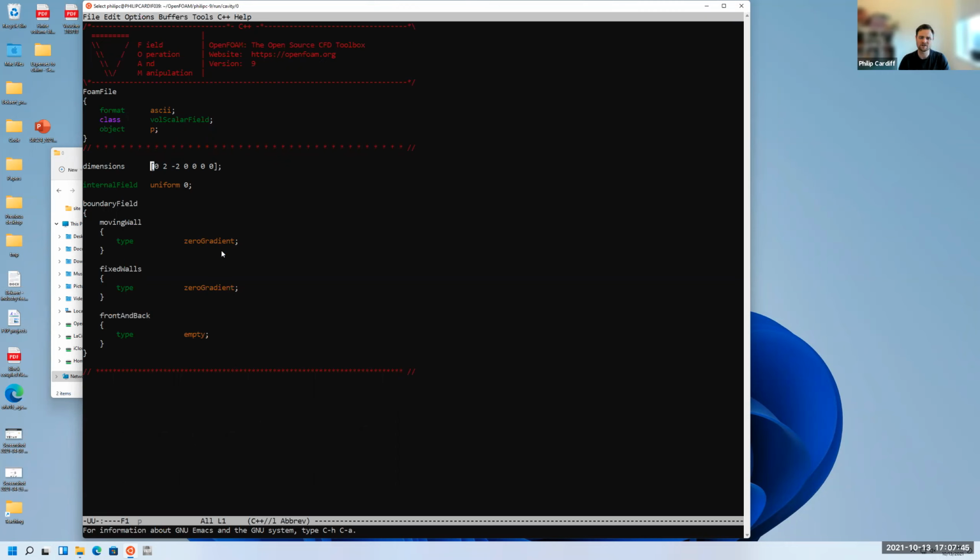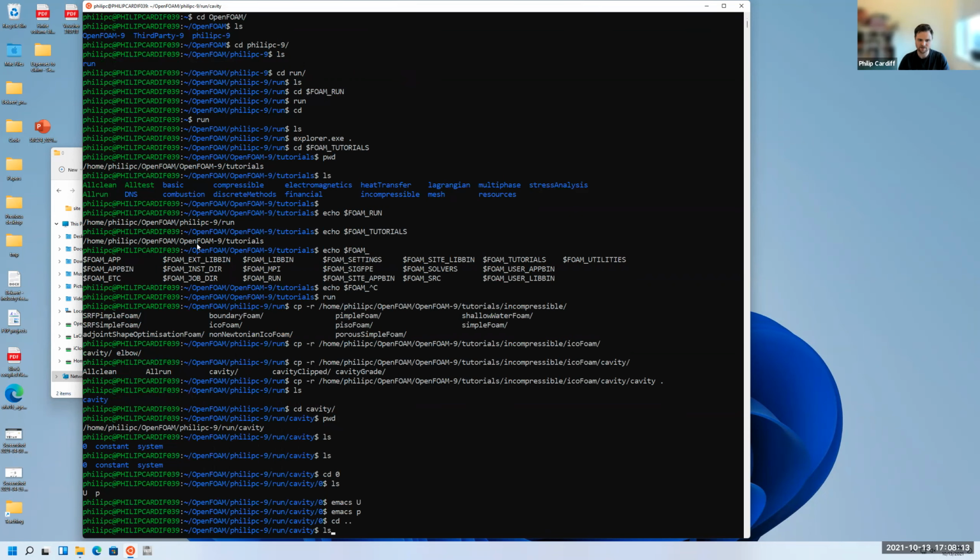And the boundary conditions here, as is typical on walls and as what Fluent will be doing, you set a 0 normal gradient of pressure at the boundary. So you don't know the value of pressure on a boundary. So in that case, you set the gradient of pressure to be 0. So that just means that if you're plotting the value of pressure away from the wall going into the fluid, just close to the wall, you're assuming that it doesn't vary as you go away. So holding control, press XC to close the file. So that's the 0 directory.